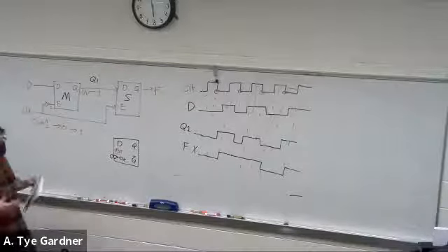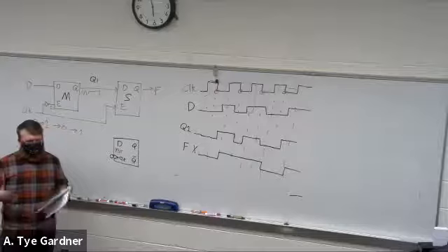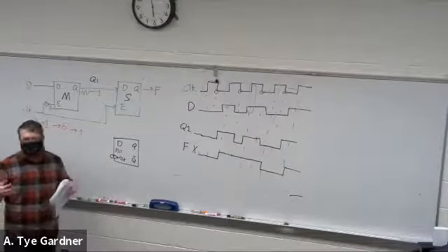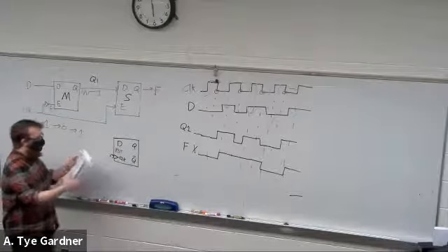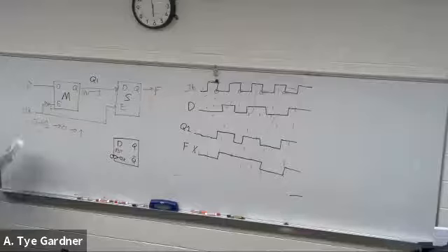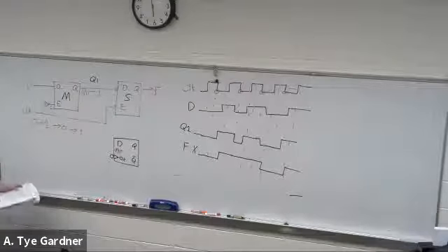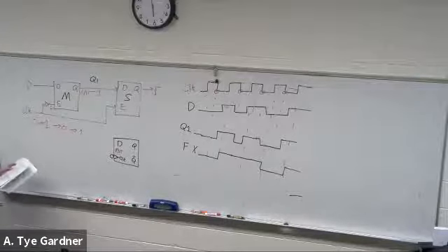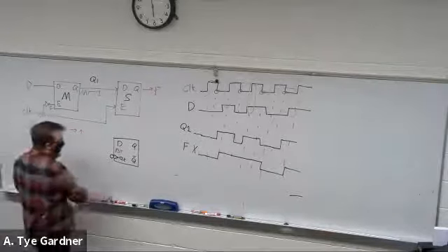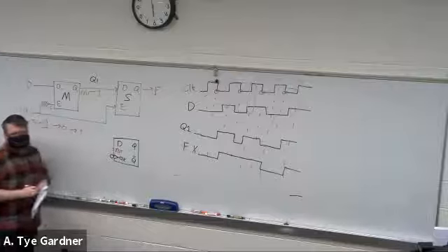It's a way of saying we need a common place to start from. Because if we don't know where we start, sometimes we don't know what the set or reset is. Well, set or reset is obvious. But we're going to learn something called a JK flip-flop that is maybe not so obvious. But that's all a reset is doing. You'll see it notated RST. And very, very often it will be active low.